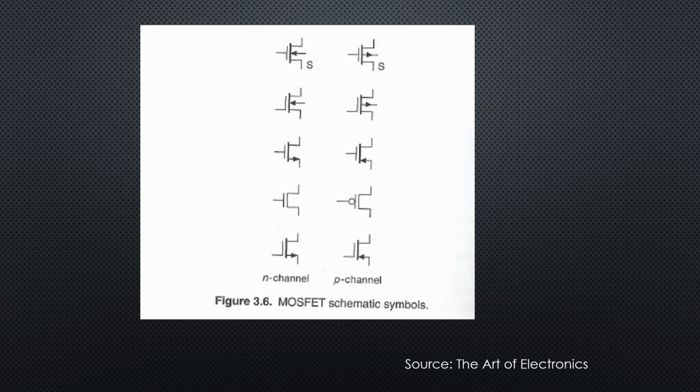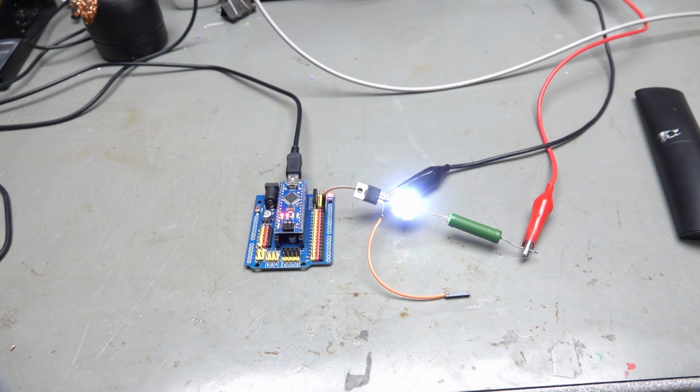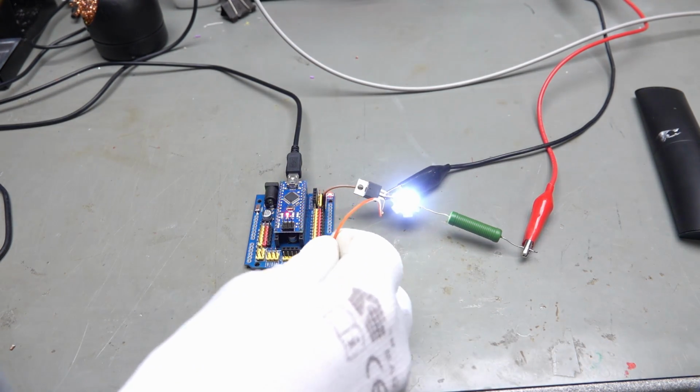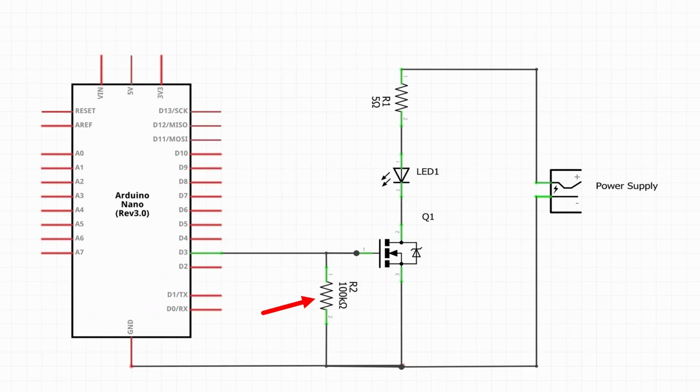As seen before, the gate is completely isolated. If I touch it with my hands, it gets a very small charge, which is sufficient to switch the channel on. Incredible! By the way, this charge easily stays there for an hour or so. Only if I connect the gate to ground, the LED is switched off. This is why you often find a resistor between gate and source.